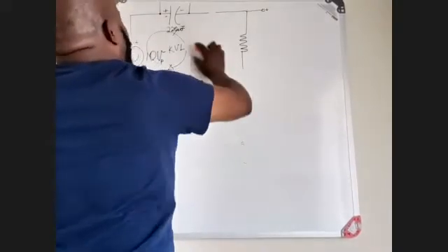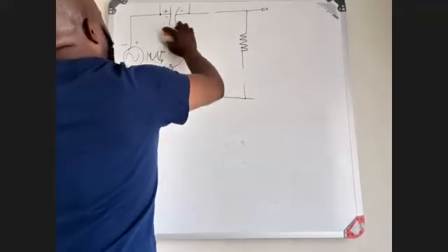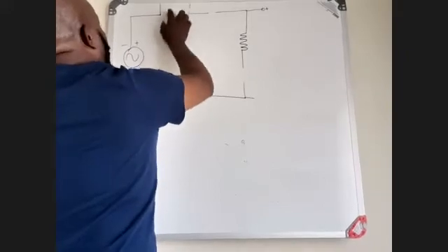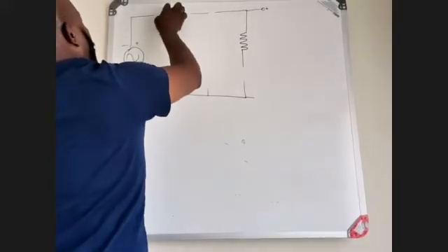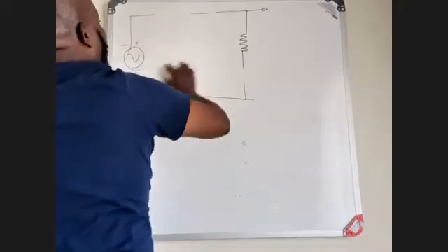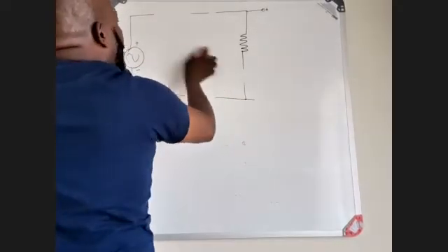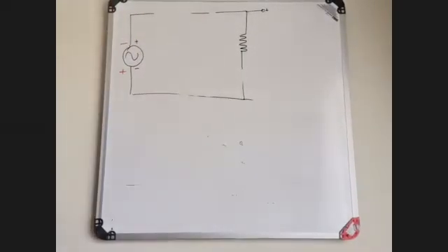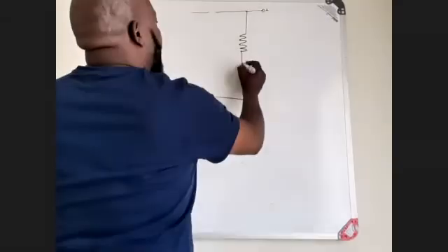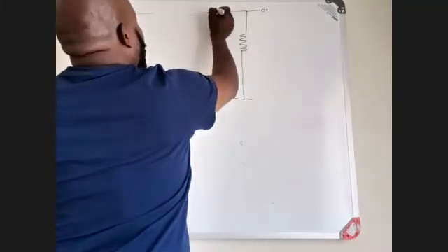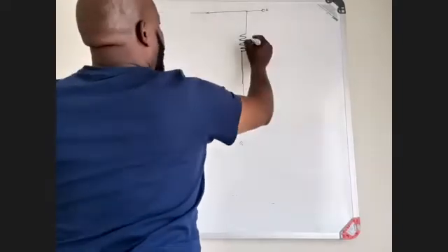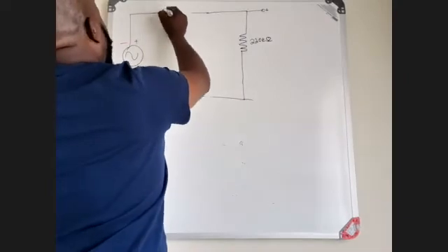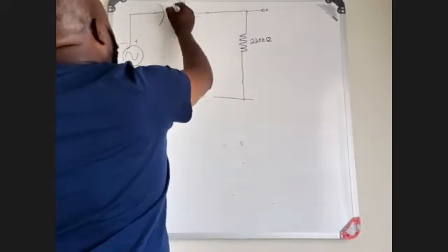As a positive clamper circuit, you use the same circuit components, but now the connection is going to be different. So you must be able to check how the connection of your components is. Now, the resistor will stay as it is, which is 220 kilo ohm. Then your capacitor is connected in this manner.